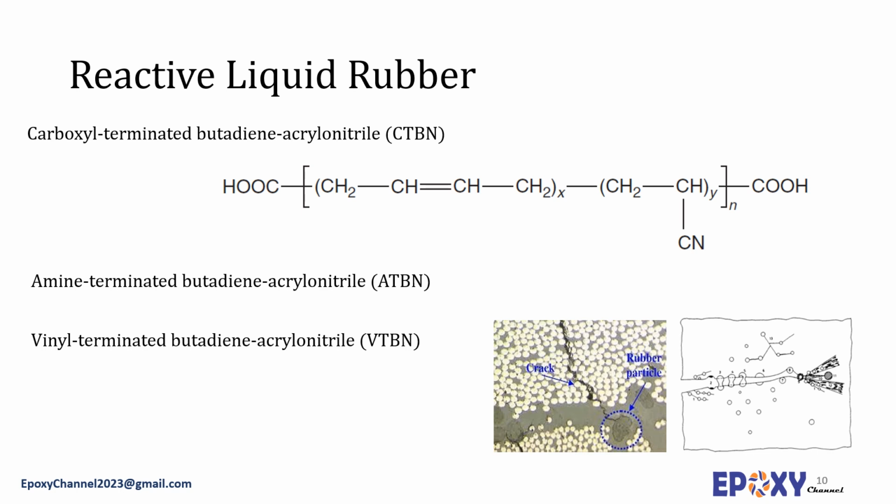Compared to unmodified epoxy, the toughened formulation exhibits significantly higher peel strength and moderately higher tensile shear strength. One of the disadvantages of CTBN epoxy adhesives has been their high viscosity, which limits additional formulation options. ATBN liquid toughening agents are synthesized by the reaction of CTBN polymer with an amine.